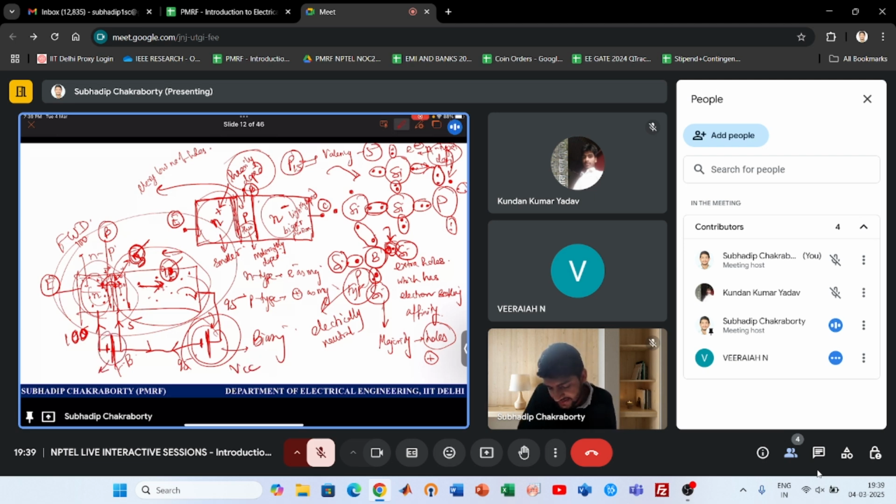The base voltage was VBE, the base-emitter voltage. That was actually the initiation of the process. Now the help was done by the VCC, or the biasing, to seek the charge carriers and actually make it happen, such that the emitter current was almost equal to the collector current. The current in the collector we call the collector current.